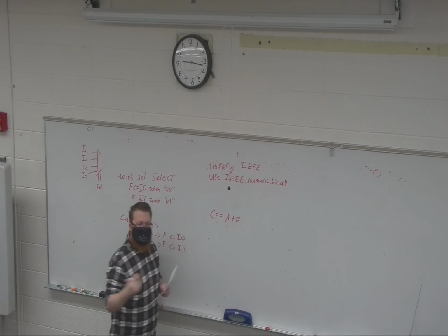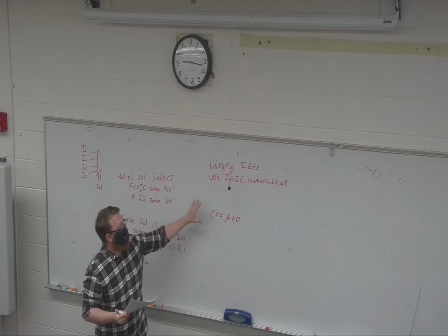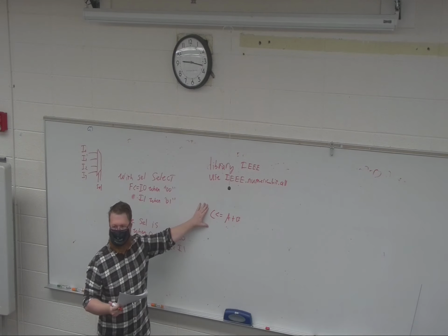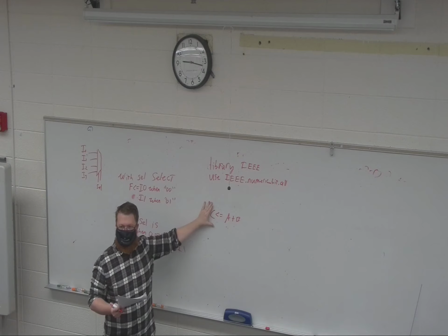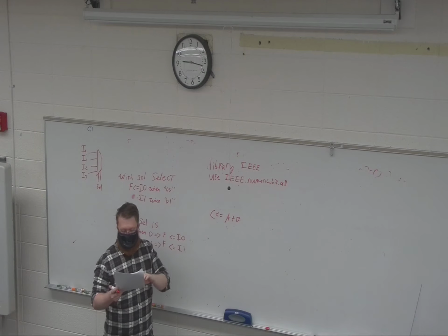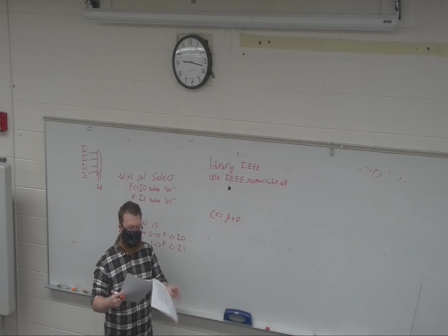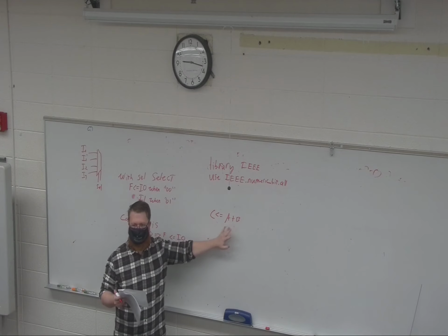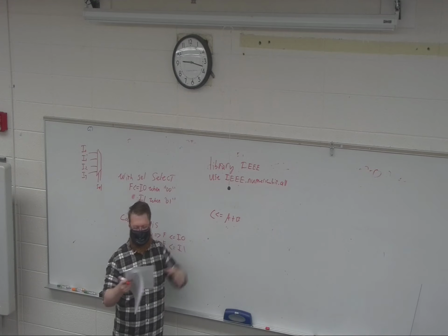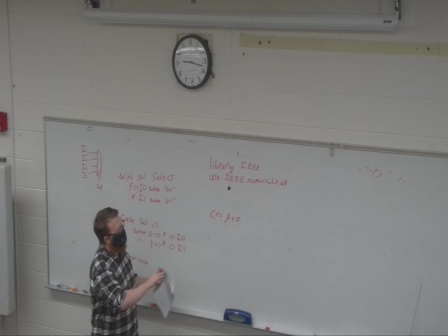So you have to be careful and make sure that you're set up. If these were bit vectors, this would not work. If these are unsigned or signed types and you have this library, this will work just fine. This will add them together. So it's going to give you all types of operators for this: plus, minus, multiplication, remainder, etc., equalities. But we also want to step up to some more complicated stuff because we want to use bit vectors.